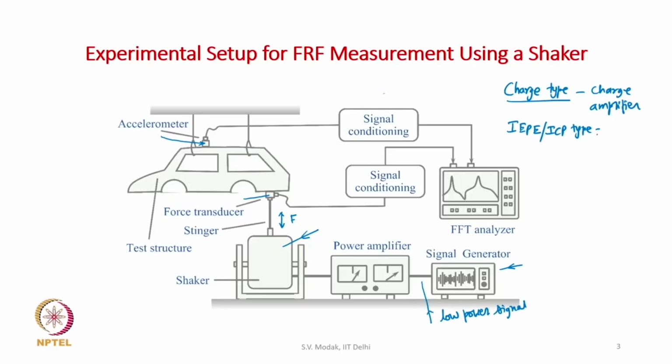In that case we do not require any signal conditioning in between; the output of such transducers can be directly fed to the FFT analyzer.